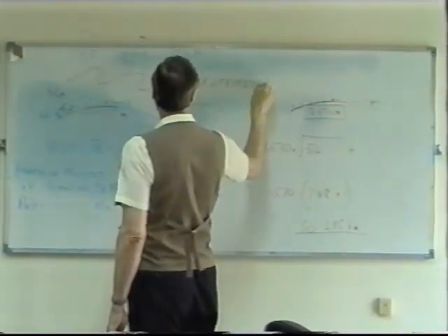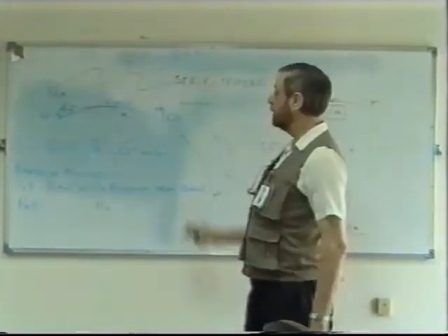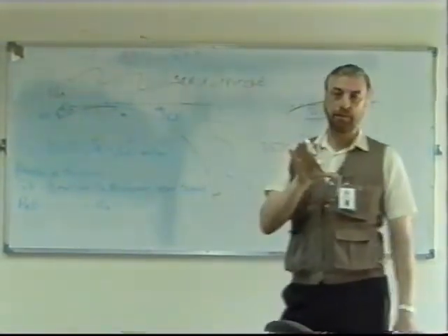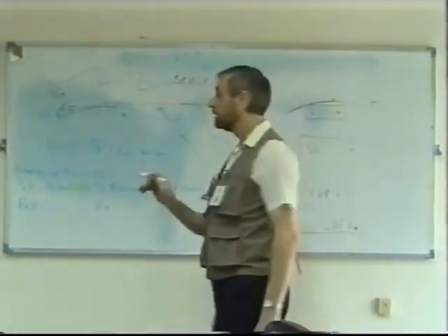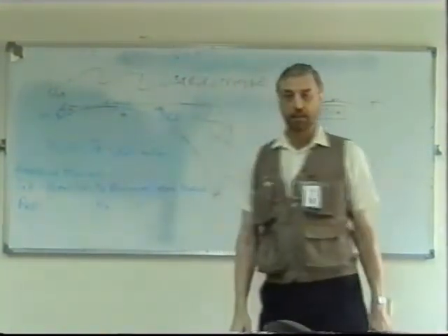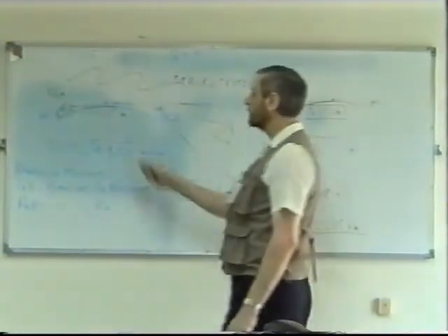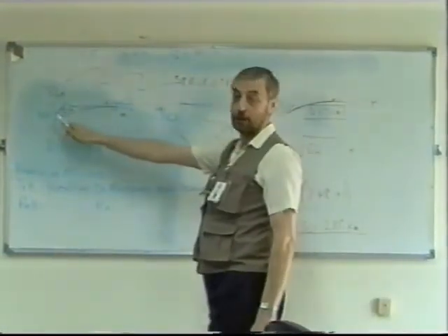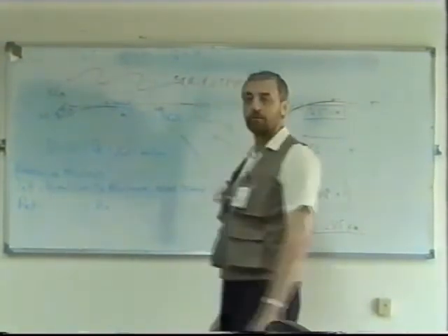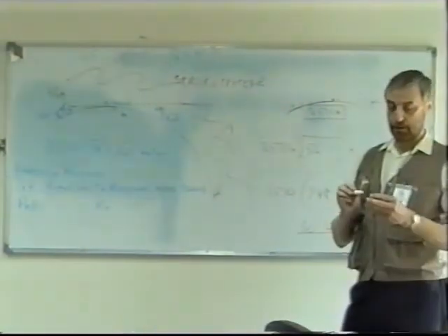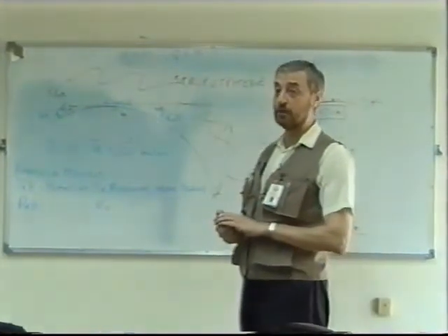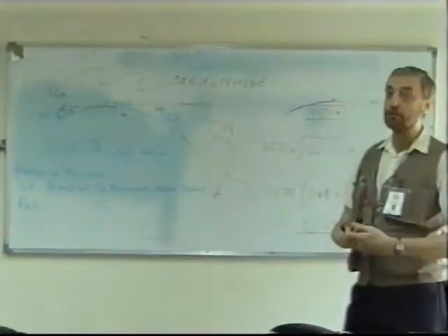Now, under certain conditions, it's possible for this wave to hit the troposphere, and a little bit like I was mentioning about the HF situation, the wave can get bent. It actually reflects off the troposphere like this. Under those conditions, you can receive obviously a lot further than the line of sight, but it's not something you could rely on totally. I would think it would change throughout the daytime and nighttime, so you couldn't guarantee it all the time.